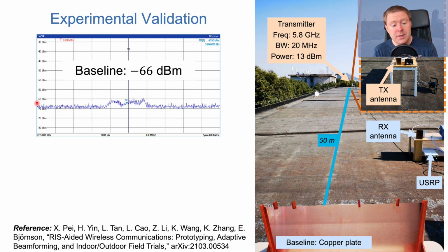And if we look at the received signal over different frequencies, this is the band, the 20 megahertz, where the signal is supposed to be. And we see small variations outside its band. This is the noise. And within the band, you can see that it's above the noise floor, but it's no big variations. The maximum number here is around minus 66 dBm.